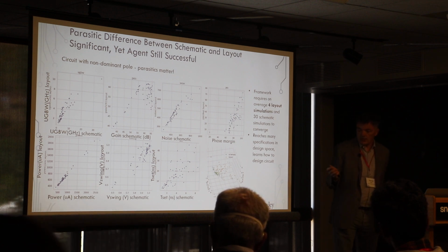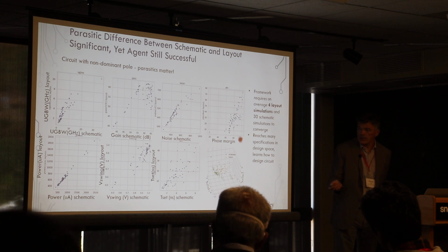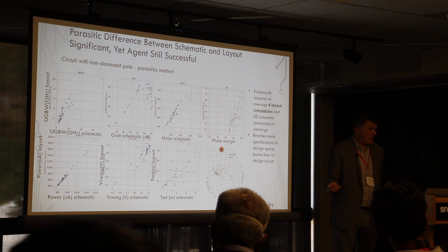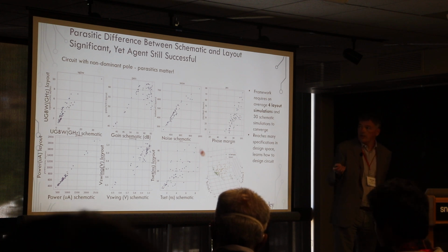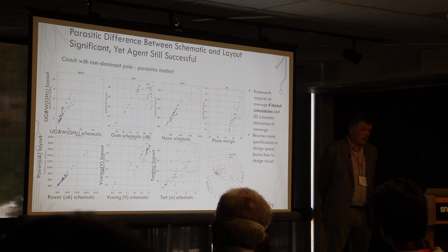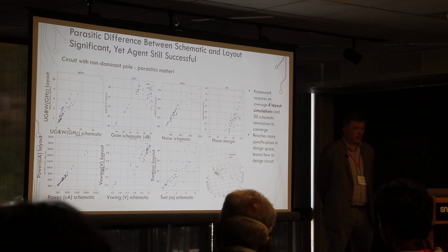So what you see here from a lot of these plots, here is a phase margin based on schematic only versus a layout. So although with schematic only, we thought we had a whole bunch of dozens of good designs, if you look over here, post layout, there are like only 3 good designs in the upper corner. So that is something that is important to remember.